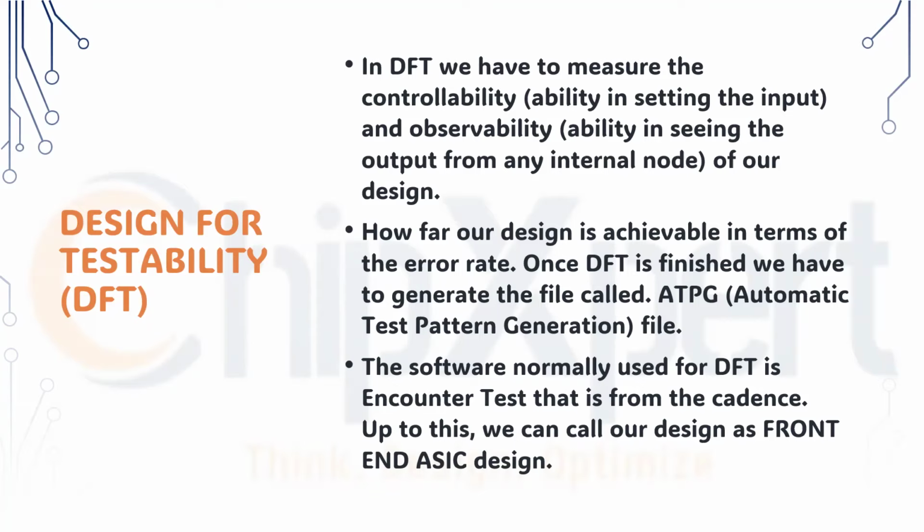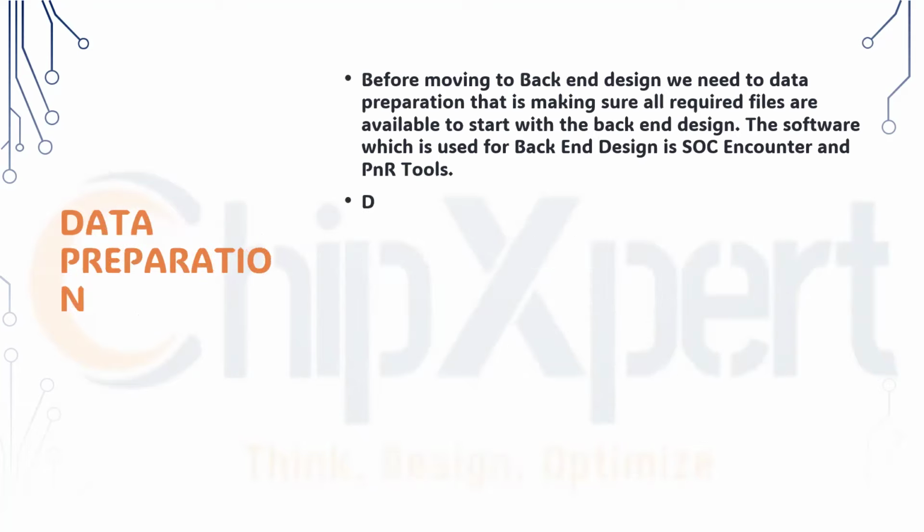So this logic is inserted. The connections will be created for each flop in the design, to check whether that flop is storing the data properly or not. Then they will test in the post-silicon process, like the post-manufacturing process. There are different software tools to test this DFT, and there are different patterns for DFT testability.